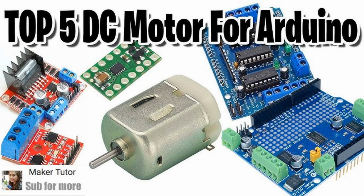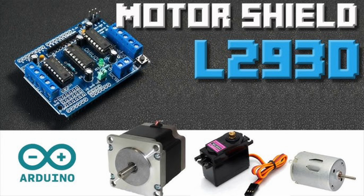The control is usually programmable via a graphical interface or communication protocol, e.g., Modbus, CANopen. Advantages: highly flexible and customizable for various industrial applications. They provide precise motion control and can execute complex motion profiles, such as trapezoidal or sinusoidal trajectories. Applications: used in automated manufacturing, packaging, material handling, and robotic systems where customizable motion sequences are required. Examples: Beckhoff servo drives, Omron servos.